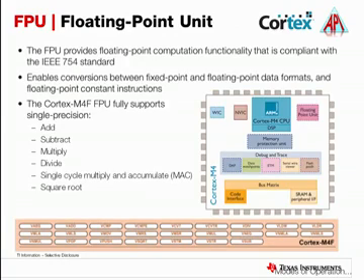Lastly, the floating point unit is another addition to the Cortex-M4F version chosen by the MSP432 family. The Cortex-M4F FPU fully supports single precision addition, subtraction, multiplication, divide, and square root, and so on. One thing to note is that FPU support is already enabled automatically in most of the compilers, so without a single click, you can already use floating point operations in your application with MSP432.